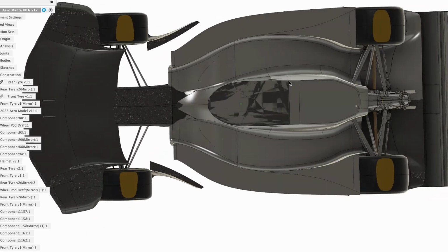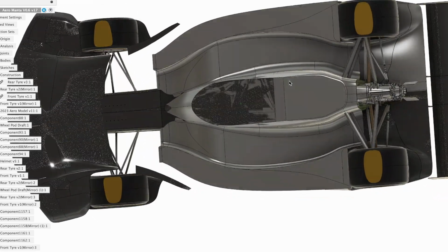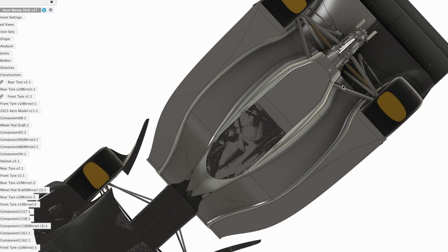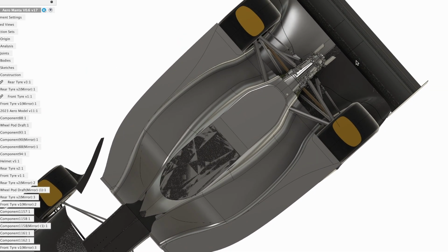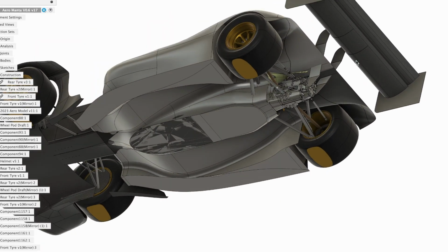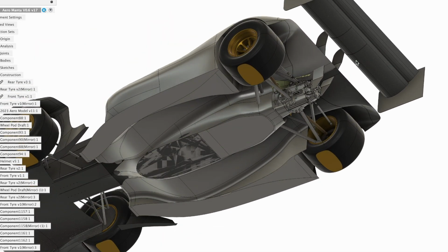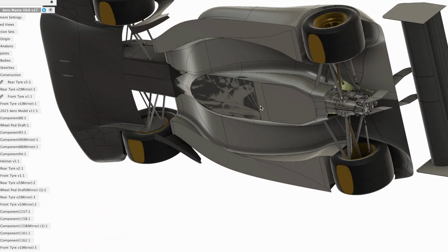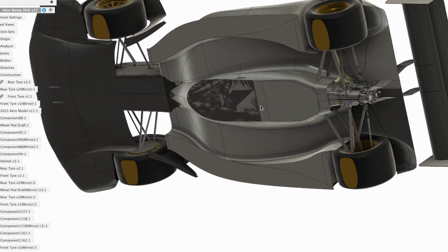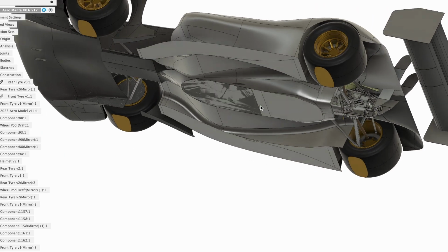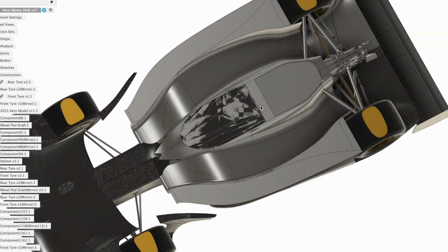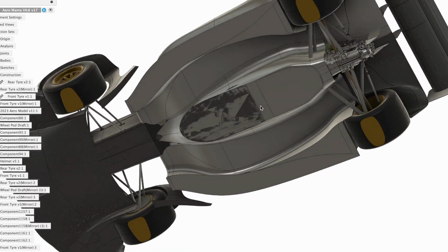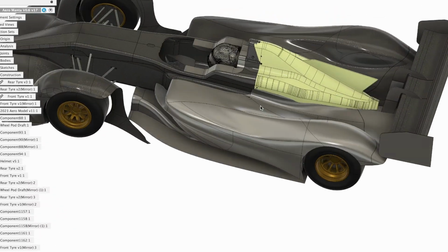So you can see on the underside, I also went to this truncated tunnel floor layout, which finished in front of the rear suspension and then just relied on the rear deck lid to carry on essentially the work of the diffuser. So it's somewhat similar to what this floor layout is compared to, like, a 1990s, early 2000s Formula Atlantic. They did this very much so. And it wasn't very efficient, but it was pretty effective in making a lot of downforce. So I stuck with this for a little bit.